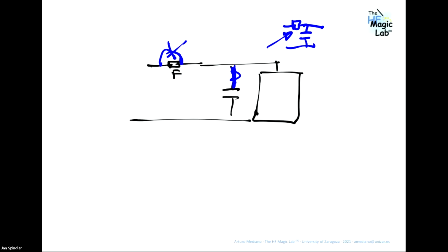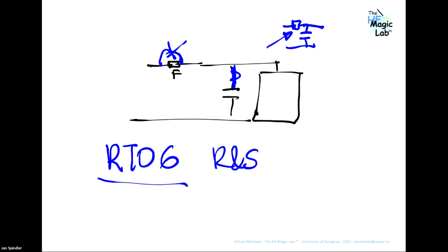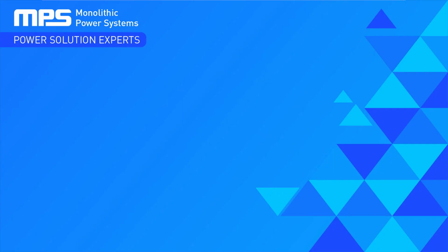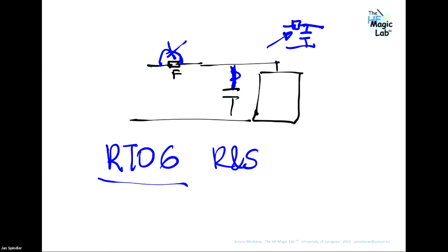It's from Rohde & Schwarz. It's an RTO. There is an RTO6, but basically you can go to any family. This is RTO6 from Rohde & Schwarz, but you can go to other families, RTM, RTE. The RTO6 is a high level oscilloscope. But the lower instruments in the family are similar because the FFT is coming with the instrument, and you will be able to do the same work. And the current probe is connected to channel number 2 with a 50 ohms input impedance to avoid reflections.